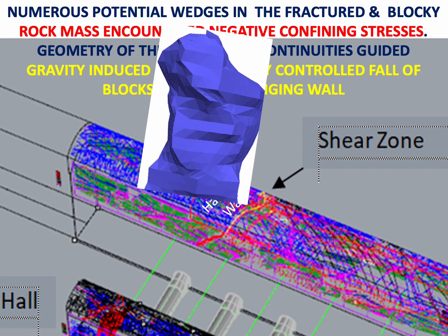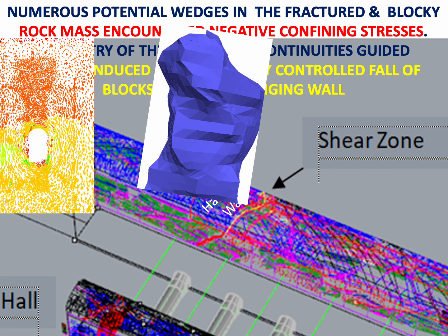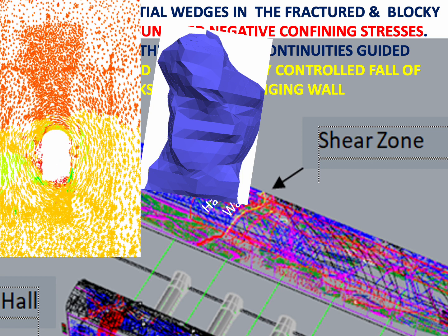It is significant to note that the shape and size of the cavity formed from the rockfall is identical to the shape of zone of relaxation seen in the plot of major principal stresses in the reach of the hanging wall, but was so seen only in the Downstream Surge Gallery and not seen so in powerhouse and transformer cavern, with minor principal stresses becoming tensile in the affected reach.